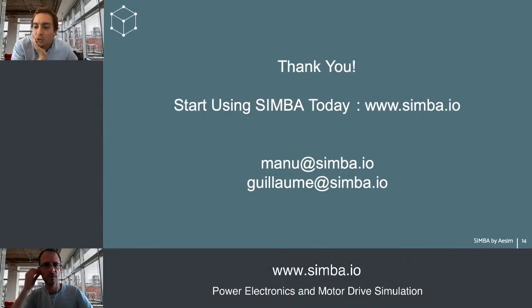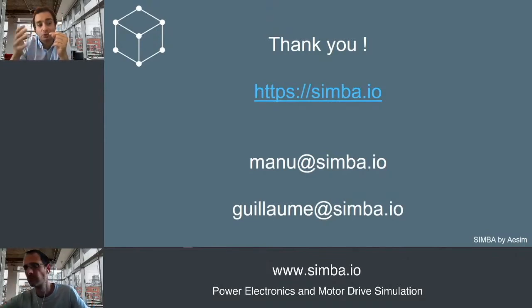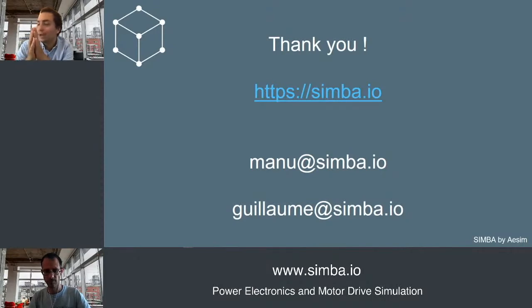Actually, I can answer. Basically, the way it works for now is for digital control, we use the C code block, and we have a default template for Z domain transfer function, and we use an external clock. So you can specify the sample rate that you want, and the Z domain transfer function will be evaluated at a given sample rate. And this is completely independent. This will work fine even if you use a variable time step solver.